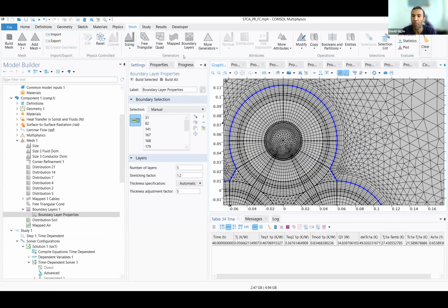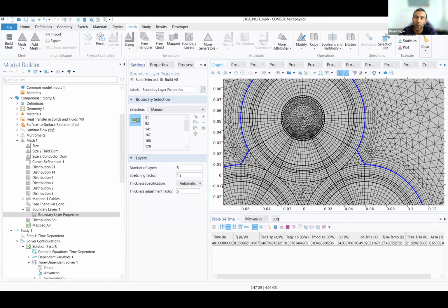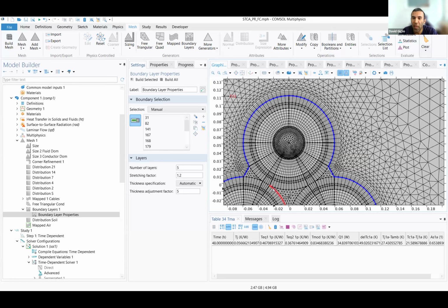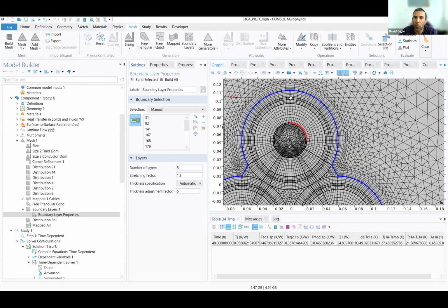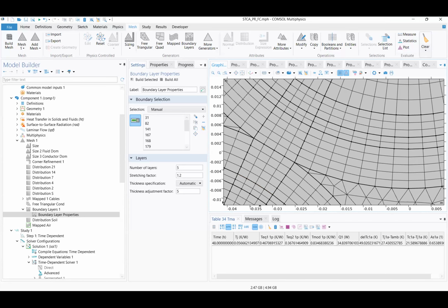If the geometry is symmetric, like a cylinder, although here I modified the cable surface to have contact with each other. So here it's flat, so it's not really a true cylinder, but it's cylindrical enough that I could apply an operation to distribute the elements. Zoom in there, please, where you put it flat, because this is very important.